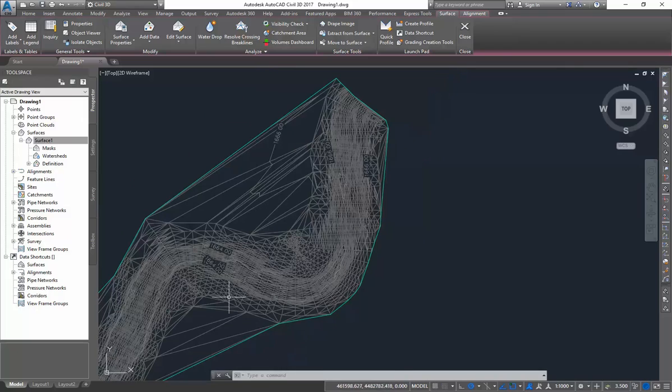So it's also good to look at the TIN because it tells you where you should have some doubts if you're trying to do design in here or estimate earthwork or build a structure along the river. You actually don't have much survey data in there, and so any of these points along the TIN should be considered really only rough estimates.